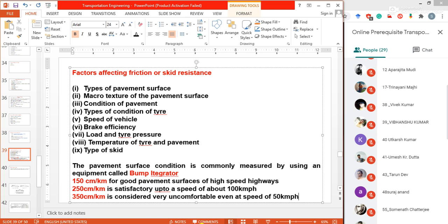Pavement undulation is also sometimes measured using straight edges, in terms of extent of number of depressions or ruts across the pavement. An unevenness indicator has been designed and patented by Central Road Research Institute, New Delhi. This equipment is useful to indicate unevenness value from 3 to 20 mm.